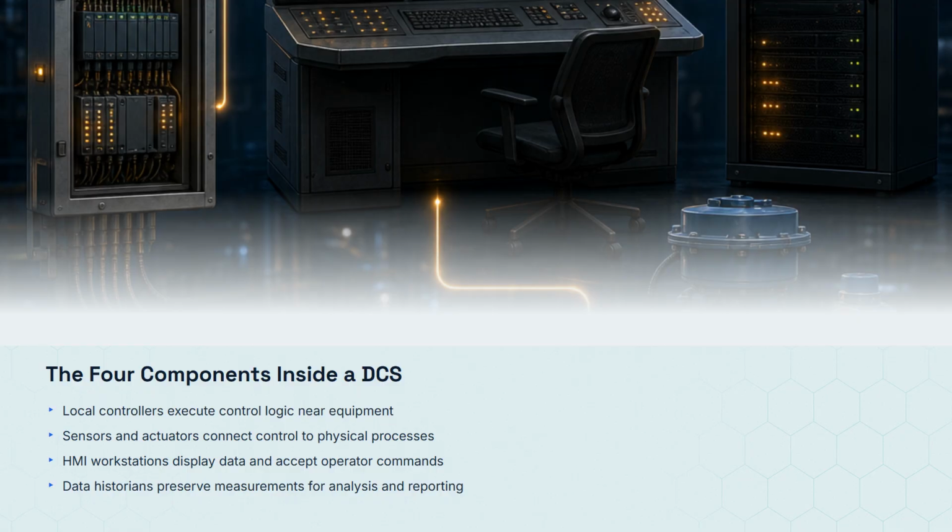Sensors and actuators are the physical layer. Sensors measure temperature, pressure, and flow. Actuators open valves, start pumps, and stop motors. The human-machine interface is the operator workstation in the control room, where process data is displayed and operators issue commands. The data historian is a specialized database that records every process measurement over time for analysis, audit, and regulatory reporting.